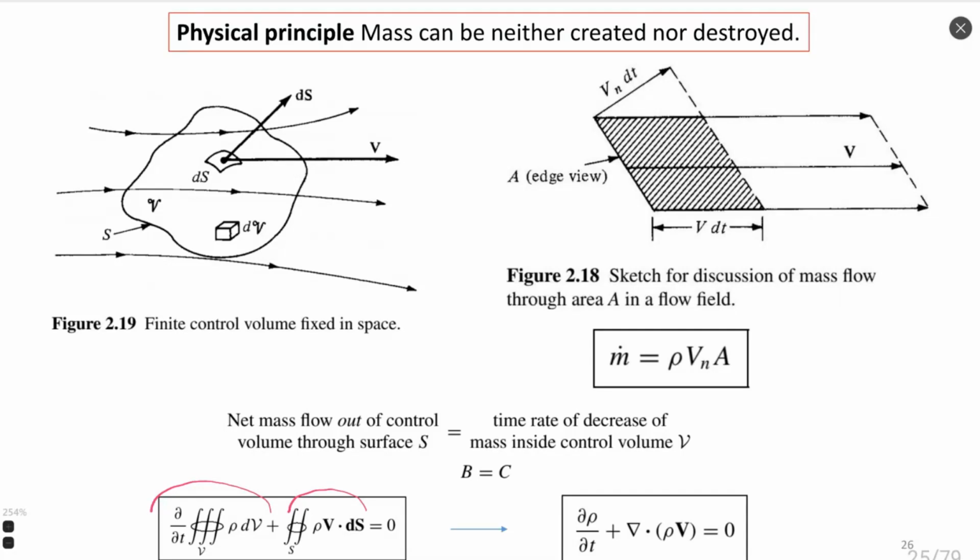Another comment about these equations, which you can see on the bottom: there are 2 types of equations we are usually looking at in aerodynamics. Equation written in integral form with integrals. This equation is usually applied to control volumes. And on the right side, we can see the same equation in its differential form. It's not the same, but it's a consequence. You can find in the Anderson book how it's obtained. It's a very simple process.